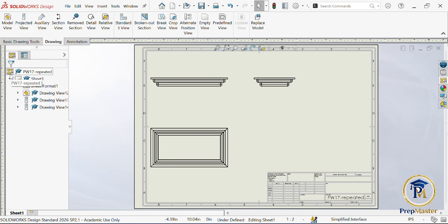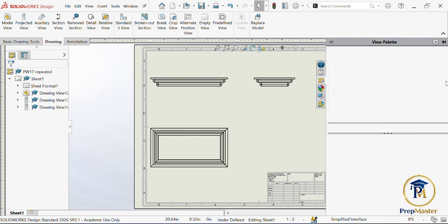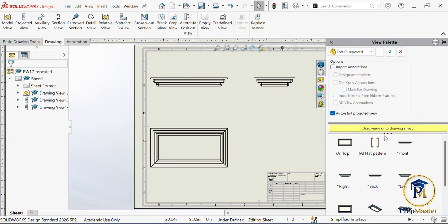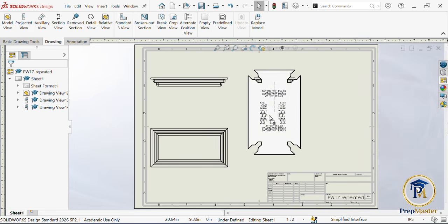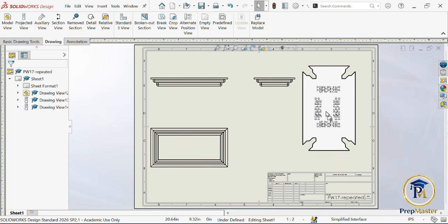As far as we have set it to first angle projection, as you can see, it's already arranged in first angle projection. So that's all we need. Now any other drawing we need, you can just come over to the left hand side and drag it. As you can see, it's much faster that way. Instead of us dragging it and arranging it, it has arranged everything for us.